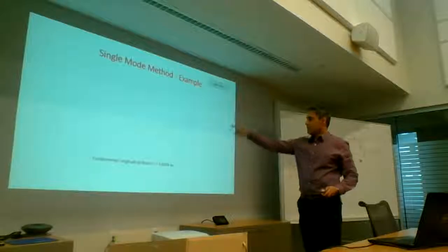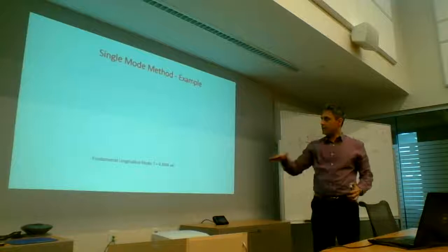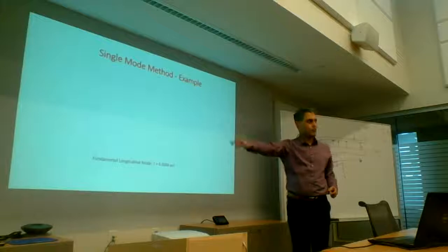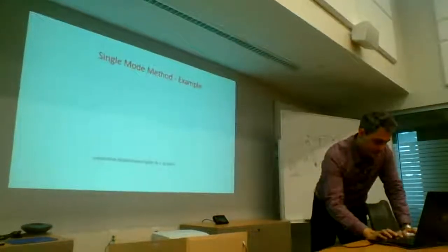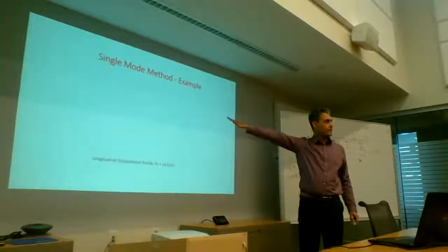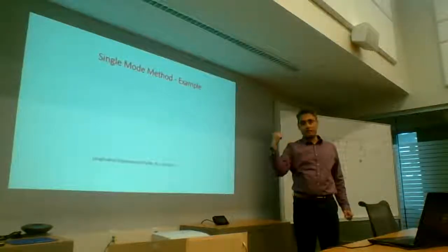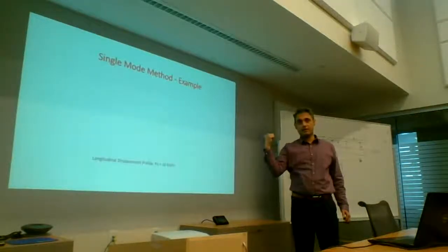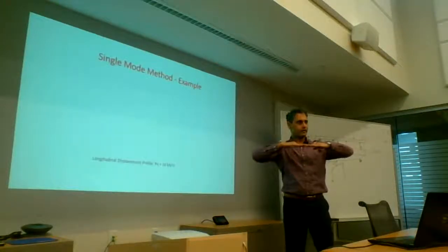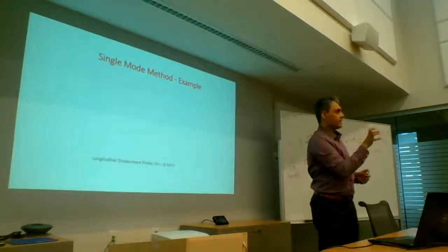This is where the deck's actual axial rigidity is modeled appropriately. So you see this hump in your mode shape. Whereas when it's very stiff, you see that it pretty much stays very, very straight. Okay, so the simplified method doesn't capture that. This method does. The simplified method just assumes it's a rigid stick because it doesn't have any way of figuring out what the local flexibility of the deck is.